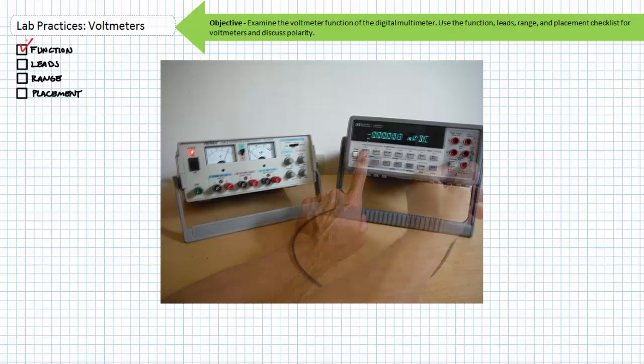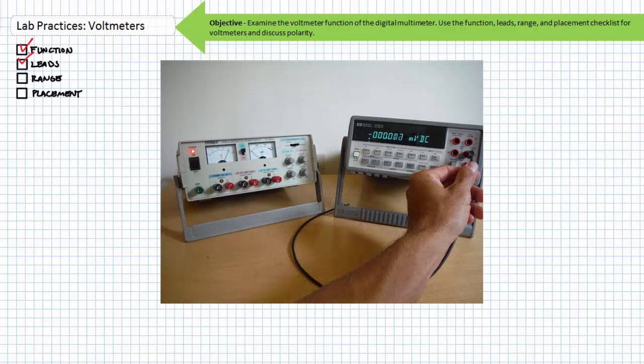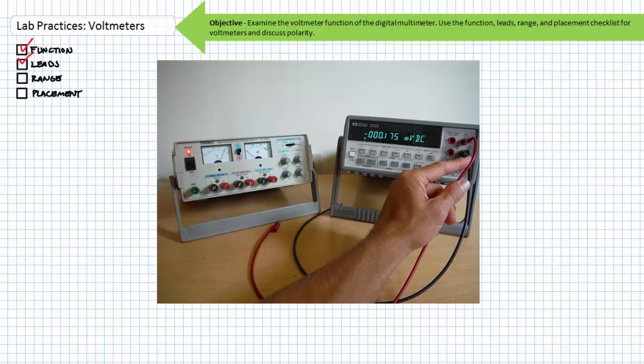Leads. Now that it's in voltmeter mode, figure out where the leads go. This meter doesn't use black to identify the common hole, for reasons I simply do not understand. The common is the center hole on the right-hand side of the 3. This is the lead that will be used as our reference. The red lead goes into the red hole, indicated with a V, the shorthand unit for volts, over it.